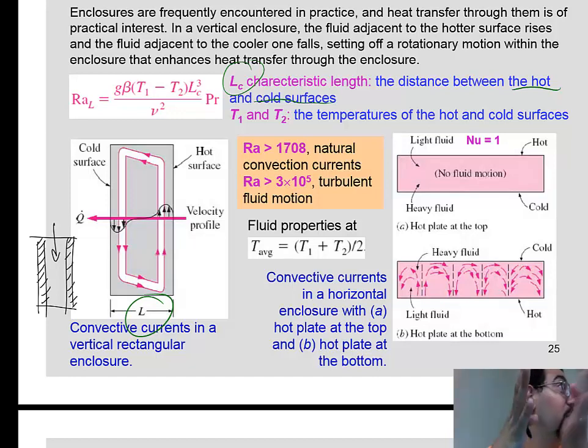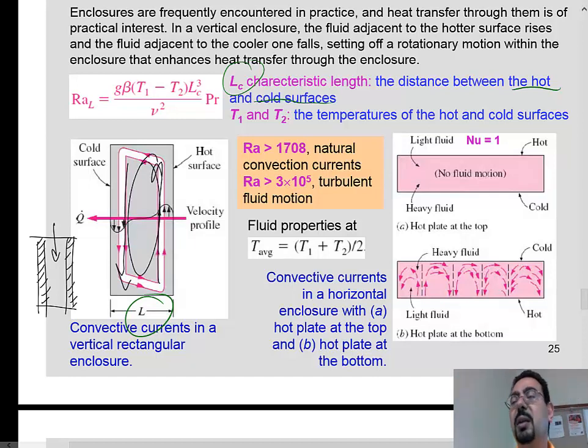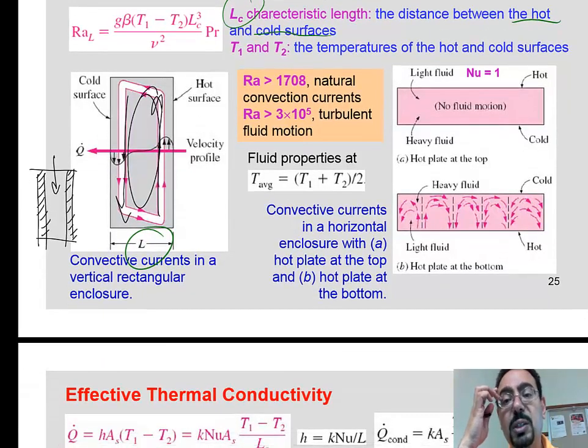So we think that when we do this double glass and we have this inert gas between them, we killed the heat transfer, right? But as a matter of fact, there could be a small cell that's moving between the hot surface and the cold surface. The cold surface will cool the fluid and take it down, while the hot one will heat it and take it up, and you basically will have this cell.